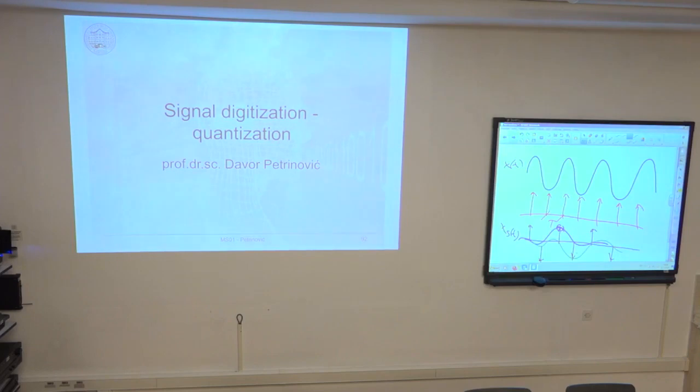And in this case, it can achieve this huge rate of gigasamples per second because it doesn't have any processing, operations like multiplication, additions. It doesn't have a successive operation of comparison like this successive approximation AD conversion.